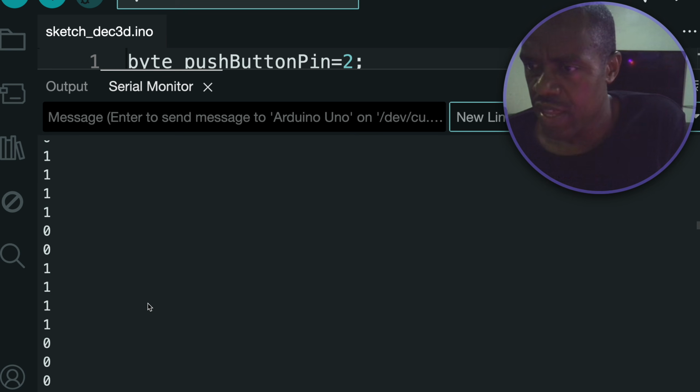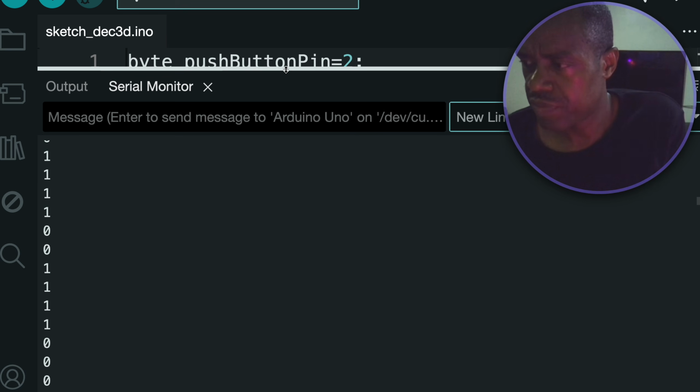The push button is currently released, but we're sometimes getting 1, sometimes getting 0. It means this is unstable, and this is the state called floating. Floating state is an undesirable state, where the signal read on the pin shows unusual behavior of being high or low uncontrollably. And this is a state to avoid.